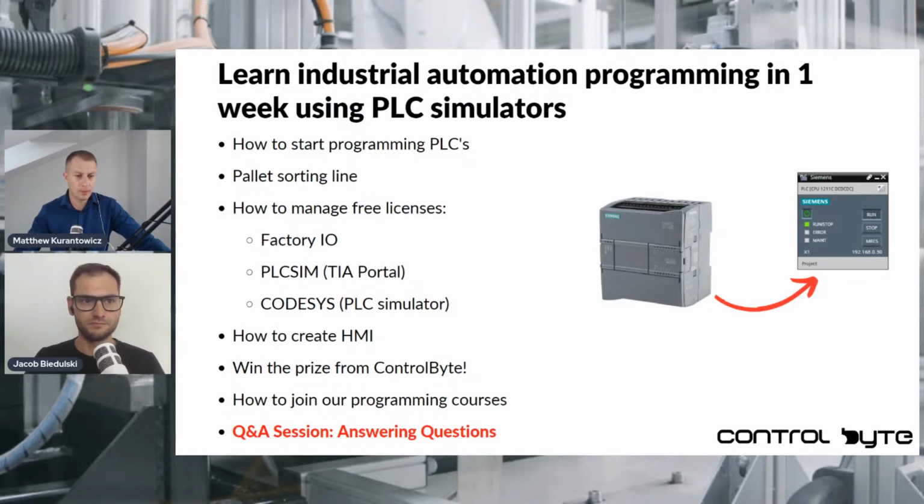Yeah, so you can use free licenses for TIA Portal from Siemens. You can download this software and run PLCSIM. This is a PLC simulator. You only need your computer and some free time to learn programming. As you can see, you can develop your project and download it to the PLC simulator. Next, you can connect that with a virtual factory thanks to Factory IO simulation software.